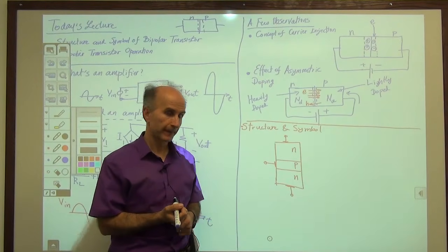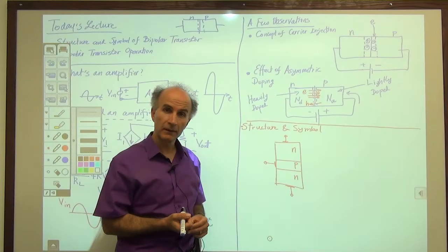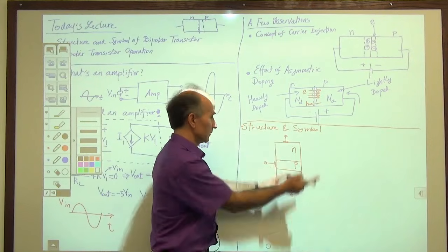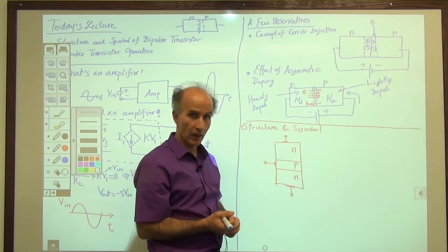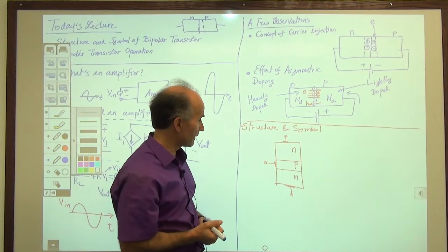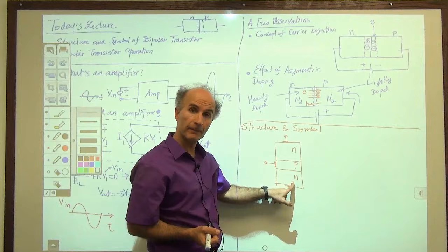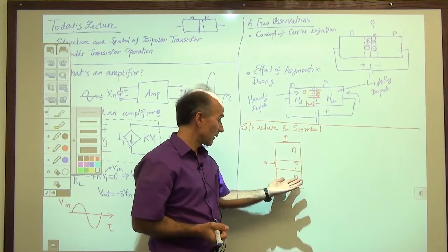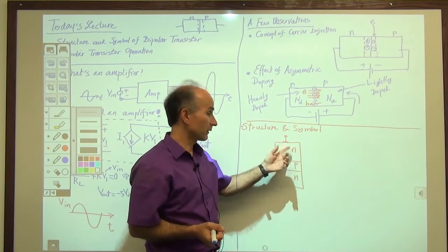All right. Is this device symmetric? Meaning, can I flip these 2 up and down? Well, no. In reality, it's not. In reality, what happens is that we want to have this asymmetric behavior here. So we will make this bottom guy heavily doped, but not this top guy.